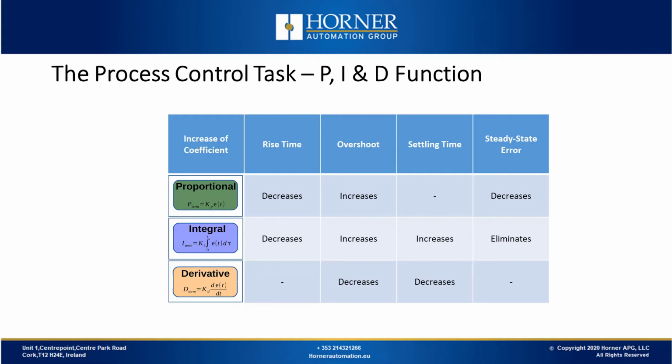Our derivative term is there to help us decrease overshoot and settling time. Those are subtleties for many processes. A little bit of overshoot or extra settling time may not matter. In those cases, eliminating the derivative term and going with a PI control may make things simpler.